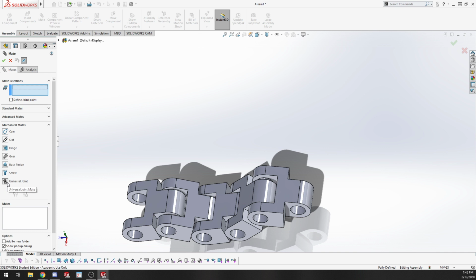And then a universal joint mate as well. That just lets you spin, transmit power at various different angles. So, for the gear mate, you don't actually have to draw in gears with specific teeth. You can draw in 2 circular things that are completely different shapes or not even touching, and then you define them based on a certain ratio.